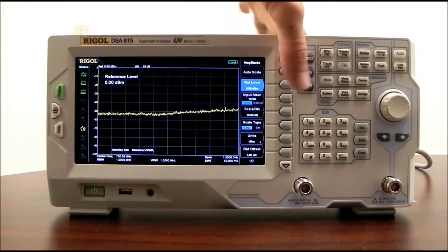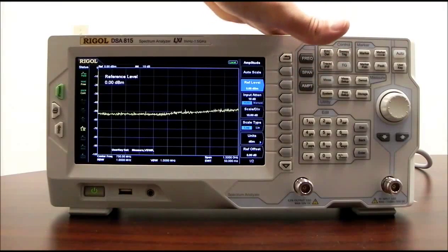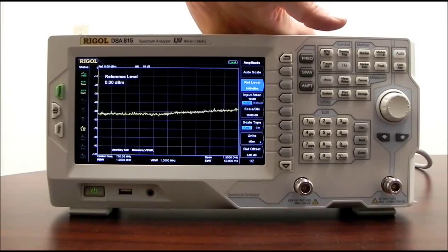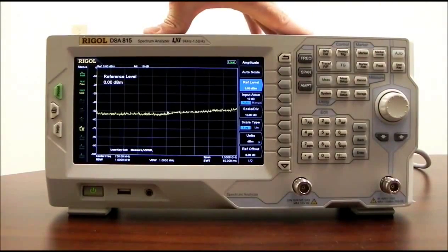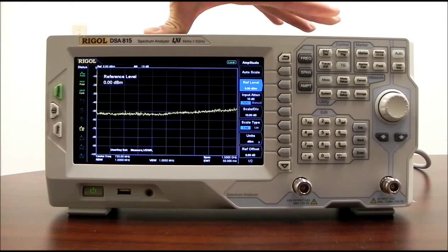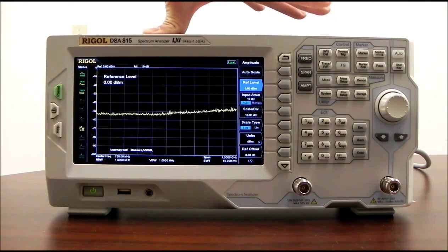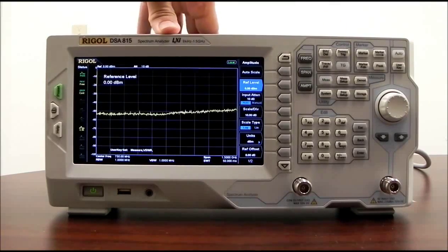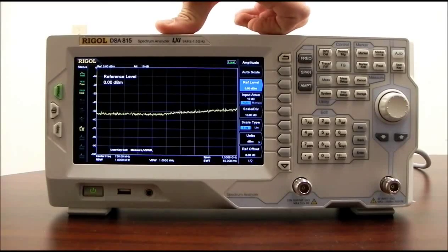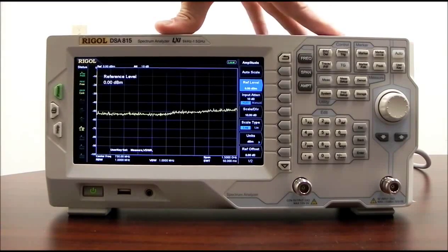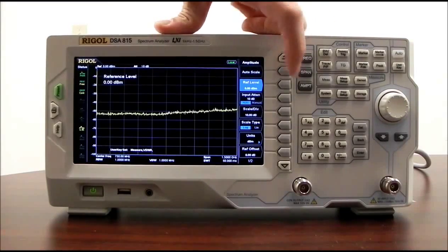And then input attenuator. So the DSA815 has an input attenuator that, as in factory defaults, automatically comes up as 10 dB. The idea is that we're going to attenuate that input just slightly, and it helps to protect the sensitive circuitry just in case you have any transients that may be discharged while you're connecting, or if you have a source that's connected that you're not entirely sure what that value is going to be. A good idea is to put in a level of attenuation in order to be able to protect that front end. Generally leave that on auto.